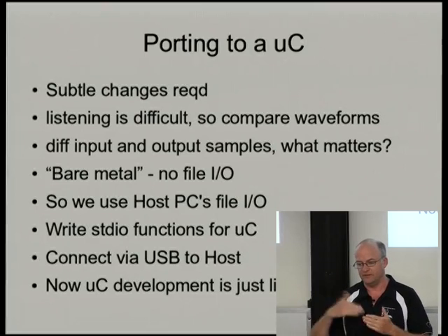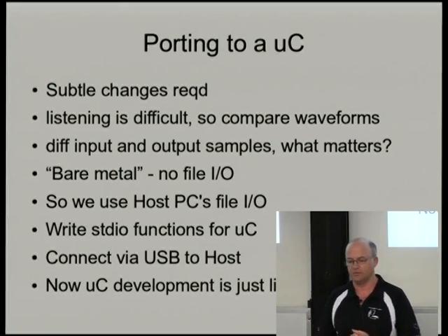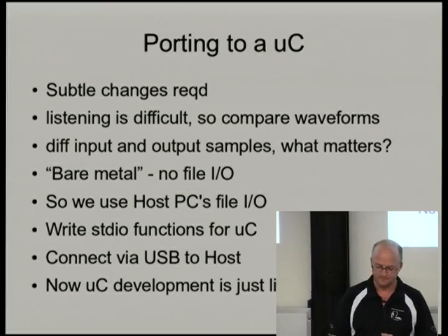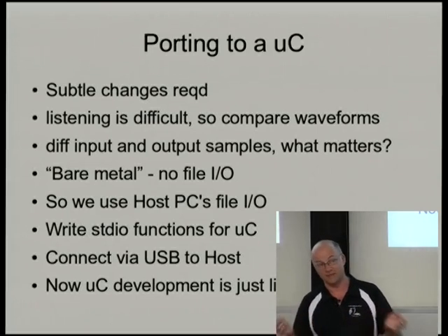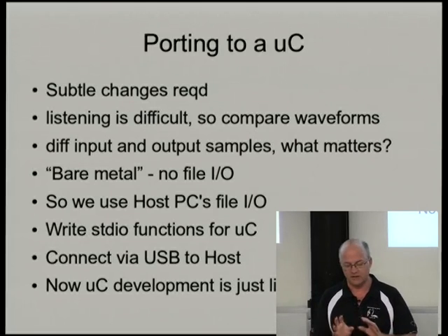There are some differences in the input and output waveforms that the ear can't hear. For example, different chips tend to have different implementations of the RAND function. I use that to generate white noise in the synthesized speech. Now, white noise doesn't really matter how you develop it. It's going to sound the same, but the waveform might be very different if it comes from a different algorithm. So for some things like that, you've either got to make sure they use the same algorithm to make it easy to test, or make an intelligent decision that, look, it is different there, but that's okay.